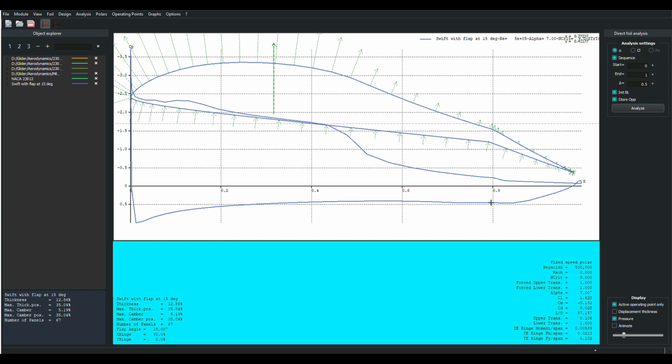And darned if we don't see our answer right here. There is no significant adverse pressure gradient wall for the flow to get through. It's just a continuing adverse pressure gradient. Most of the work has already been done. The pressure's been mostly recovered, and there's no significant barrier for the flow to get through here.